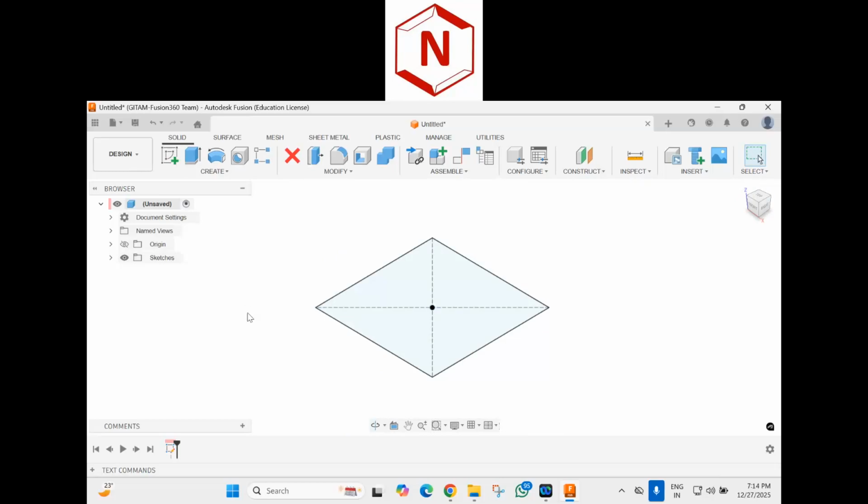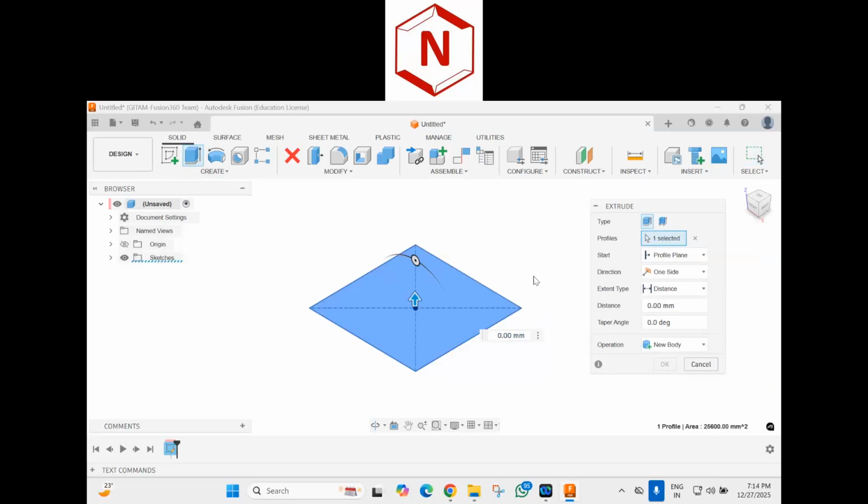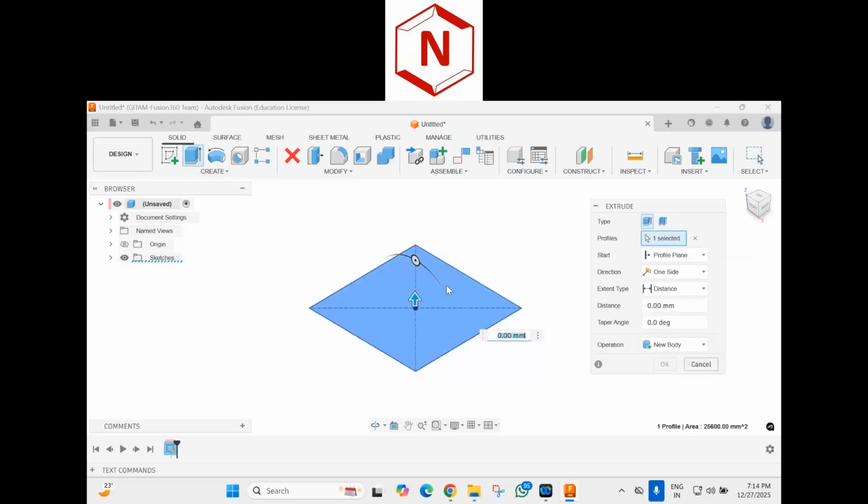Now I am going to give the thickness or height of this rectangle. For that, I am going to go to the extrude option. I will click on extrude, and you can see that the profile has already been selected. If it is not selected, we just have to click on this rectangle like this. Then there is this blue color arrow mark.